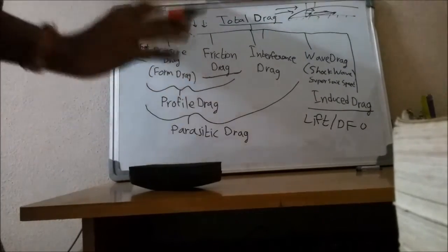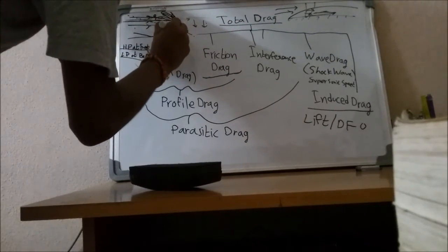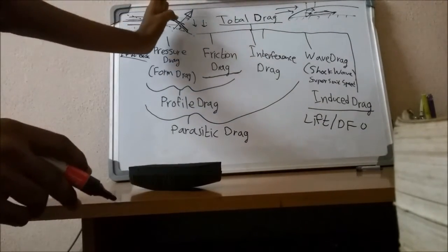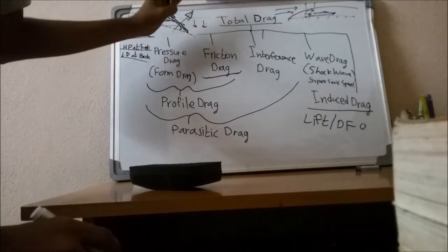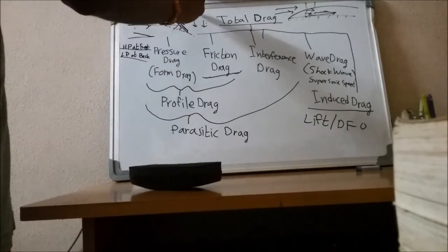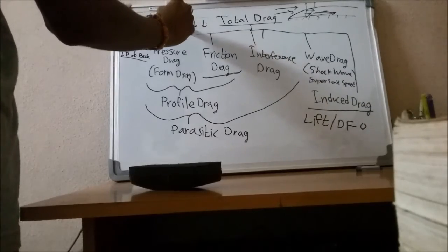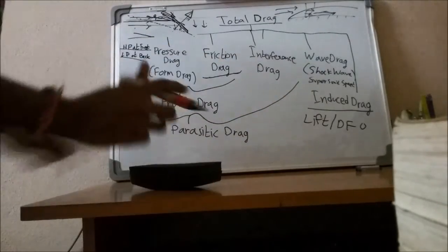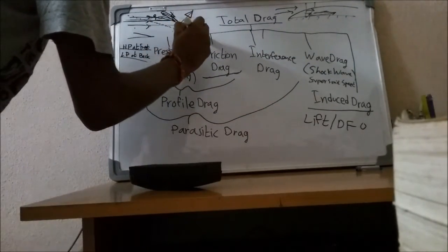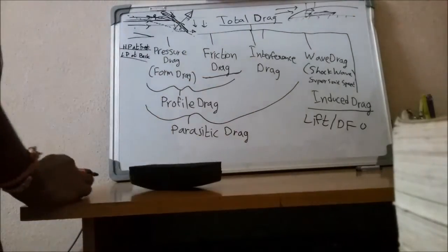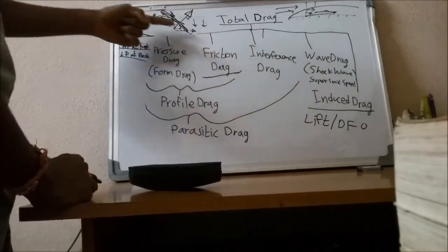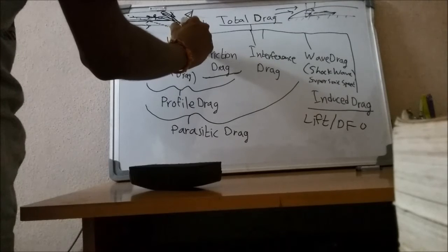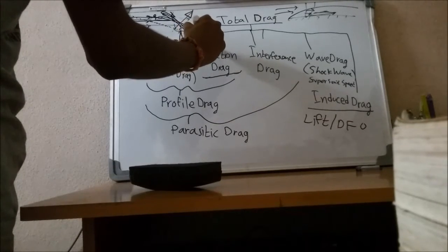Because the lift force acting on this wing is in an inclined direction. It is no more perfectly vertical, but somewhat inclined. This is the resultant lift acting. So this resultant lift will have two components. One is the vertical component, and the important point, I am finally coming to the point known as induced drag. This component is going to create a component horizontal to this flow. So this component is known as induced drag. Finally I came to this point.